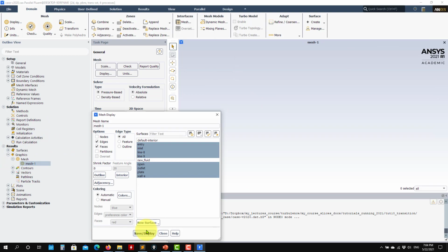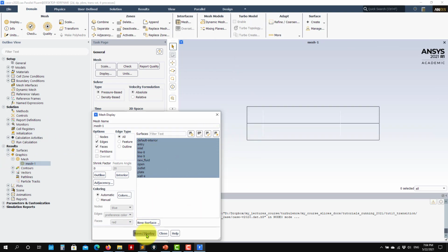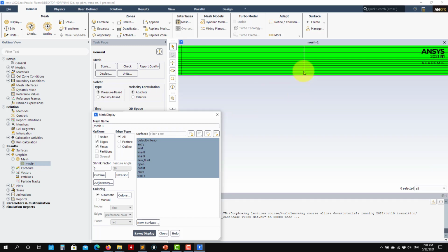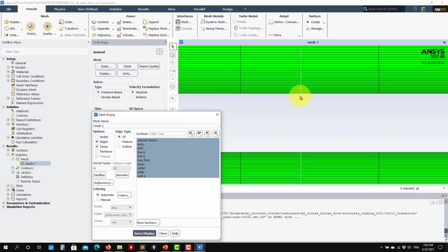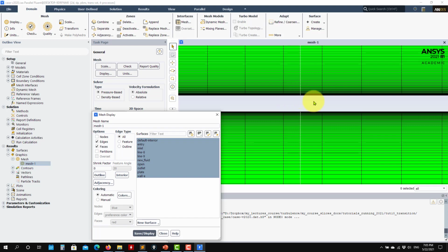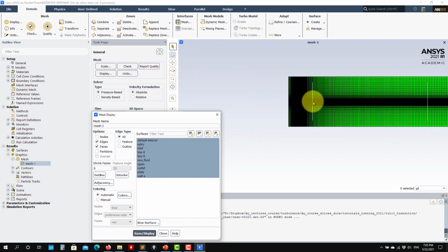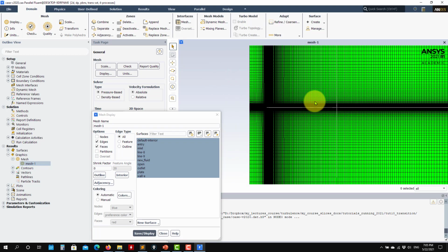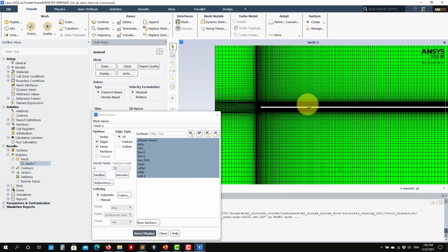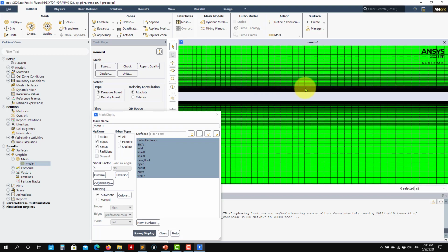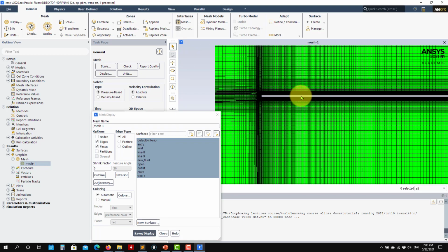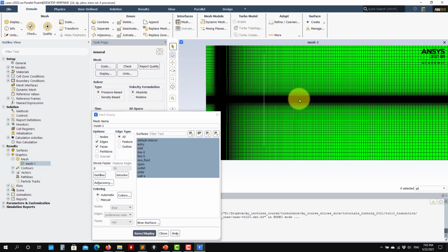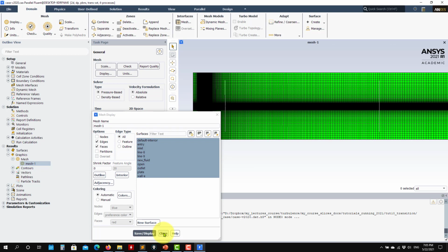Okay, so put there, select everything, and this is the mesh, and look at that. It's a very, very fine mesh in the direction normal to the wall. Not so fine in the streamwise direction, okay? But let's say that is fine enough. You can do something finer for this. Well, for this case, it is okay. But remember that in transition, that direction is also important, and you also have the third dimension. It's also important to resolve there. These white lines now represent the sampling points. So I already created those lines there.